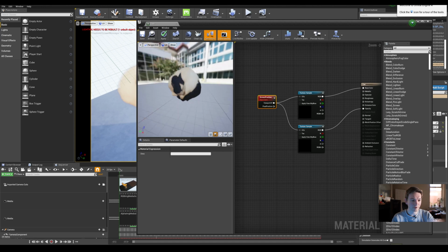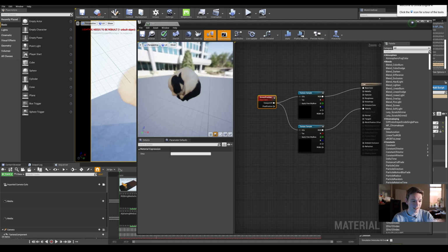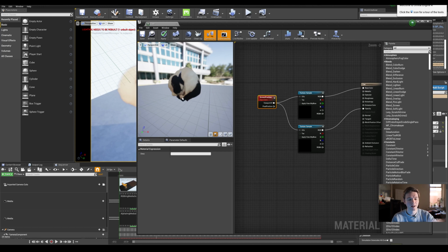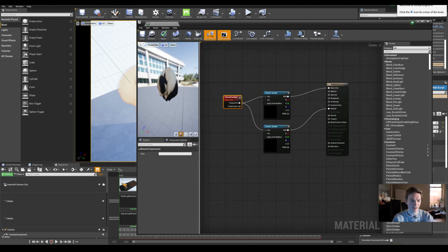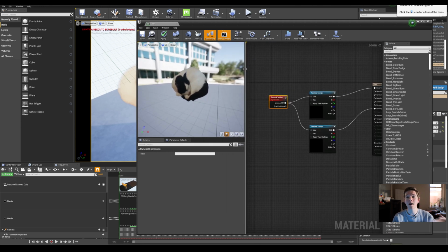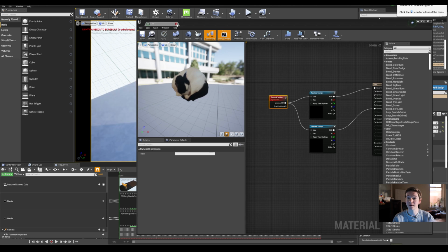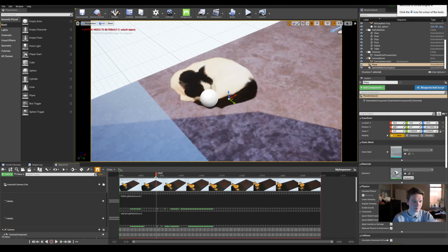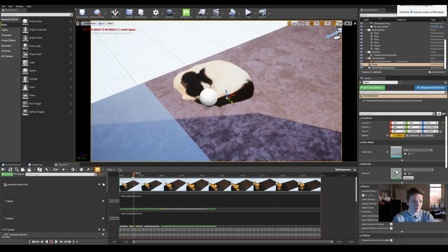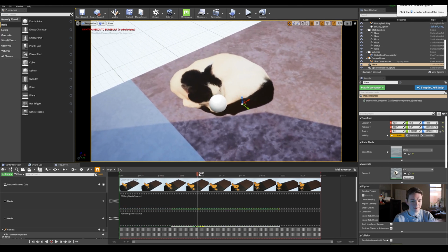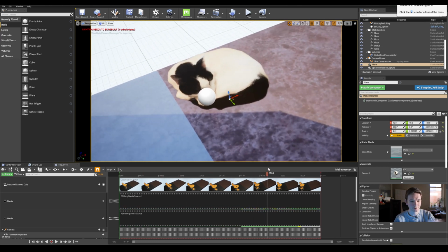Now if you drag around in the viewport, you can see it always oriented towards the camera, and it will also change its scale based on the aspect ratio of the screen. So this is looking a little stretched because the viewport here is square. If you do that, it sort of squishes, which is fine because our viewport in Unreal, if we close that and save it, is 16:9 because that's the settings to the camera. So now we've got ourselves a plane with the cat always in the right position and tracked to the virtual camera as well.